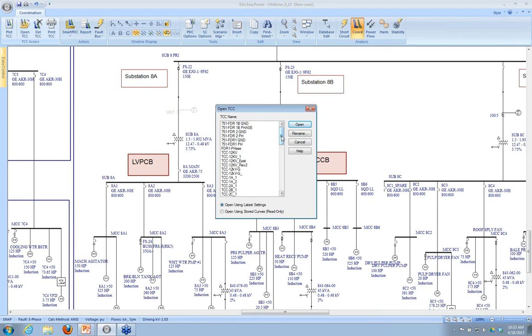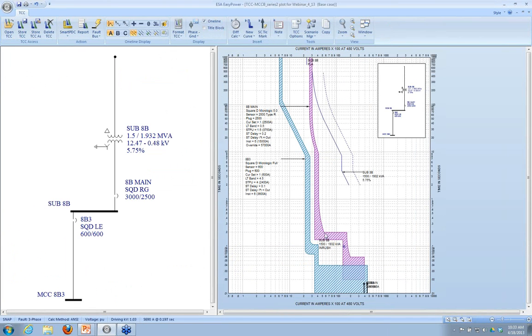And I have another example here, which is, I think, the same one we looked at before. So again, because of that, as I said before, if my fault current is down in this region somewhere, then these two will coordinate. It's only for the higher range of fault currents that these don't coordinate. So if I increase the setting, I'm improving my coordination, but it's still not perfect. There's still a risk for high current faults of these not coordinating.